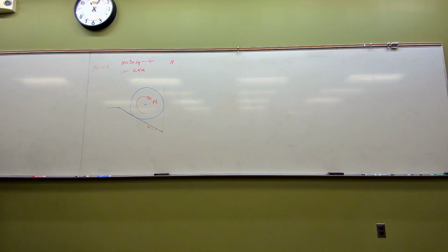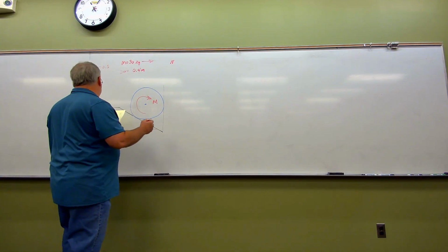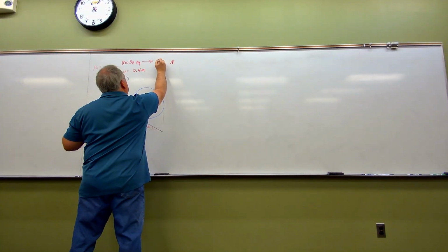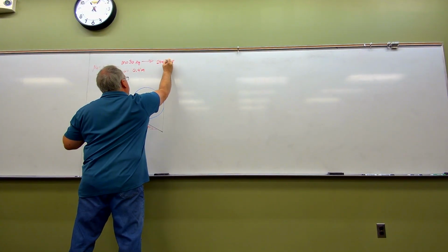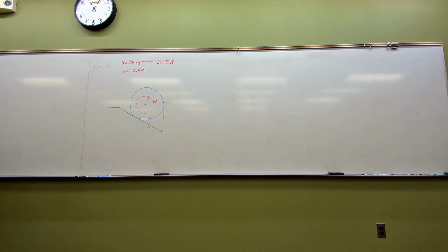Take a moment, just do a free body diagram of how would you draw the cylinder in this particular case right here, folks. And I'll get ahead of us just a little bit by pointing out that the force here, when we multiply this by 9.81, we're going to end up with 294.3 newtons. So let's just make sure we got that. So the weight here is 294.3 newtons. Take a moment and just figure out how would you do the free body on this one.